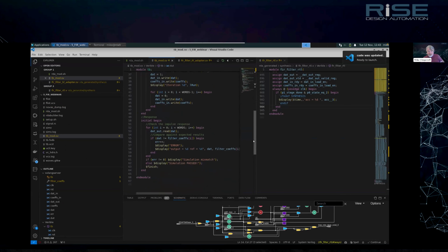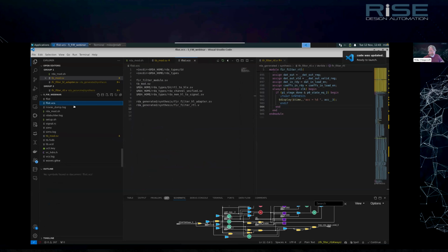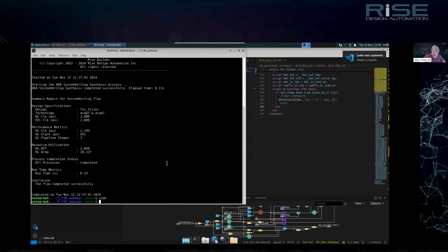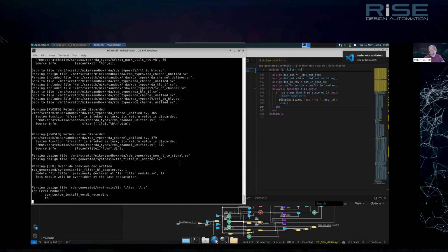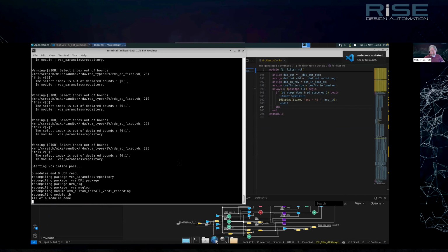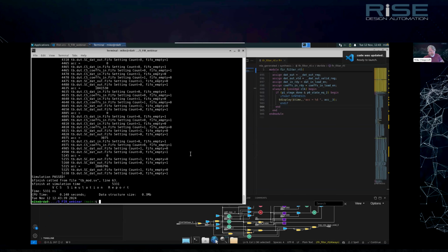and rerun verification and redo my self-checking that I've implemented in the test bench simply by running VCS. And I can show you basically here that this is my synthesis or my file list for VCS, and I'm just synthesizing the adapter at the end. And if I go ahead and I run VCS, it goes ahead, it synthesizes it, it says the RTL passed.